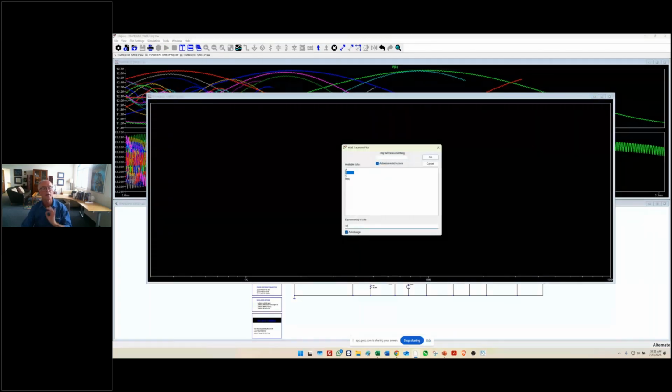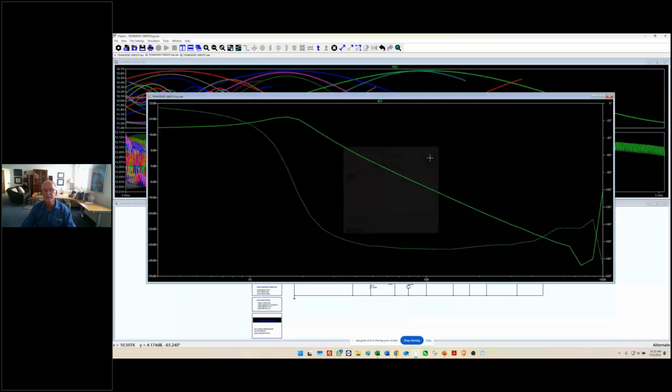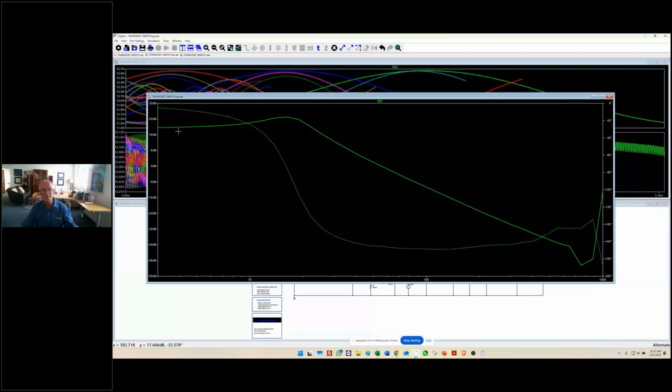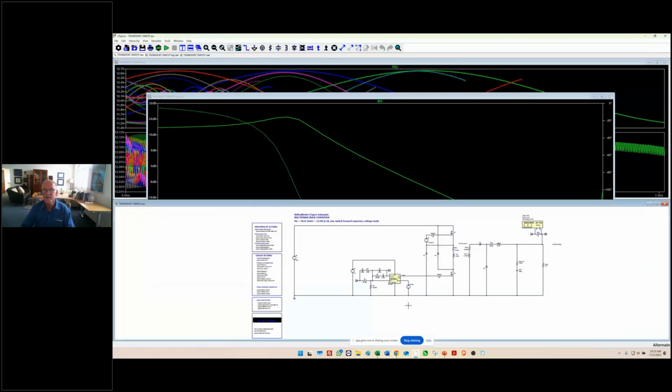So now we've got another way to generate this transfer function. And it didn't require any analysis to get the analytical expressions, and it doesn't require the small signal model. You're just running it on any large signal circuit that you can find. Even if you don't have any model to solve for your circuit, you can actually run it in LTspice and sweep the loop. So this is really nice.